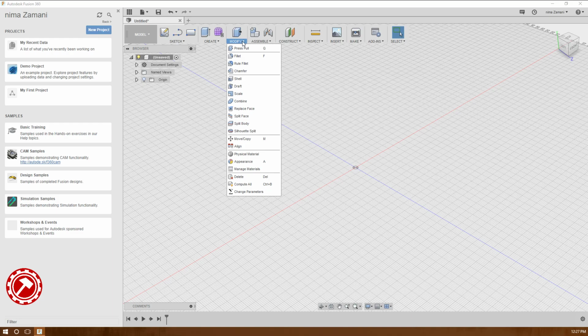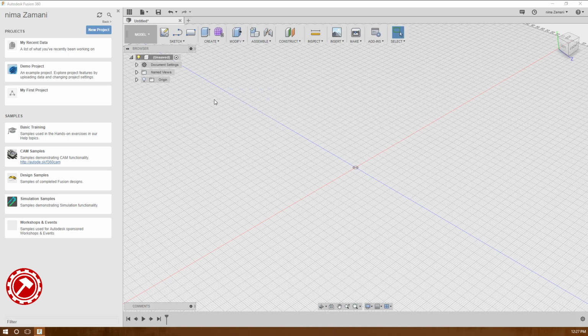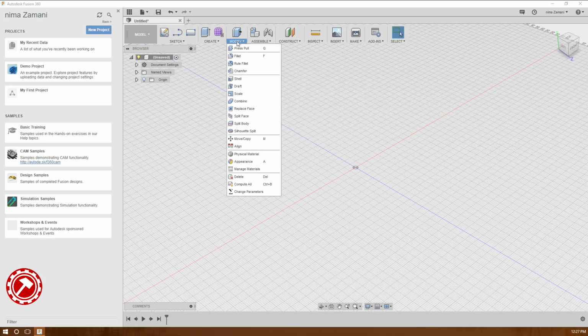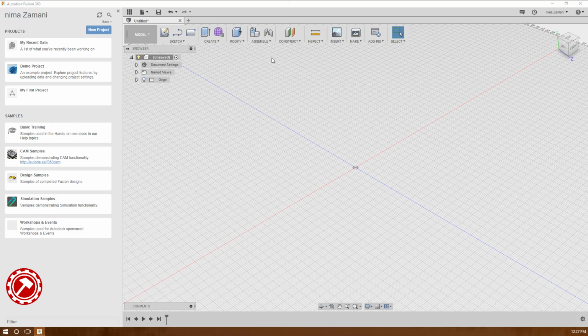features. It's also very useful and handy for times where you're importing an already made CAD from generic file types, such as STEP files or IGES or any other CAD files, where you don't have access to the underlying features and you don't have access to the history, but you want to change some features. You can easily do it with the modify menu. And we're going to go over all these later on in more detailed tutorial sessions.